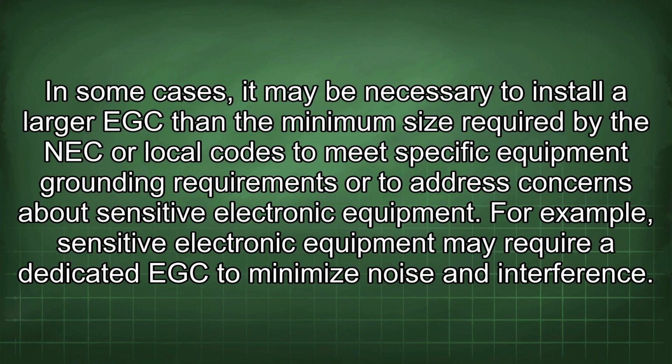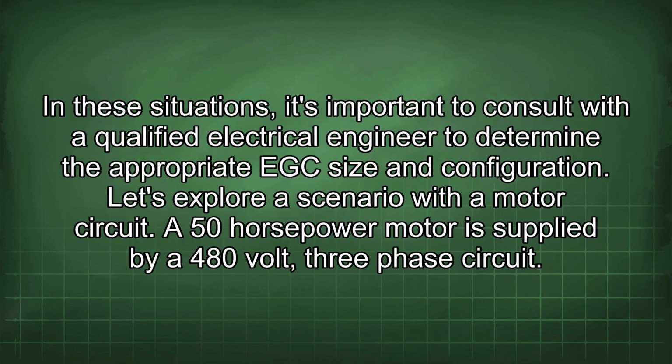In some cases, it may be necessary to install a larger EGC than the minimum size required by the NEC or local codes to meet specific equipment grounding requirements or to address concerns about sensitive electronic equipment. For example, sensitive electronic equipment may require a dedicated EGC to minimize noise and interference. In these situations, it's important to consult with a qualified electrical engineer to determine the appropriate EGC size and configuration.